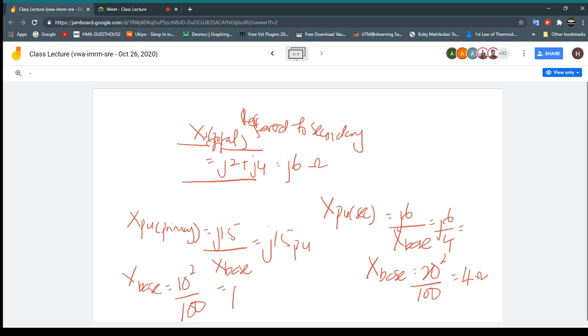Now the total reactance looking at the primary. This one is the existing primary reactance, 1 ohm, j1, plus j0.5. So I get j1.5. So this is the equivalent circuit referred to the primary. So any questions so far? No. Okay.